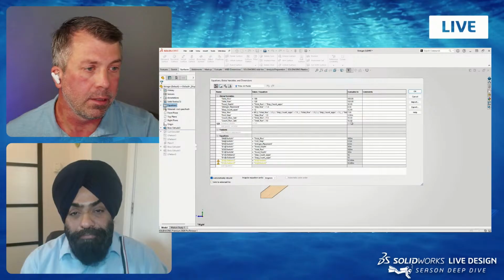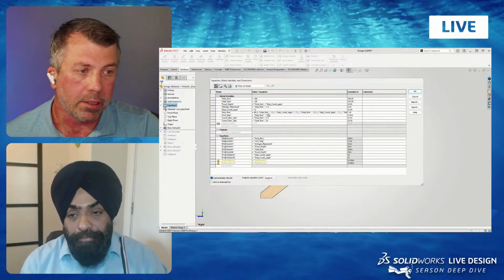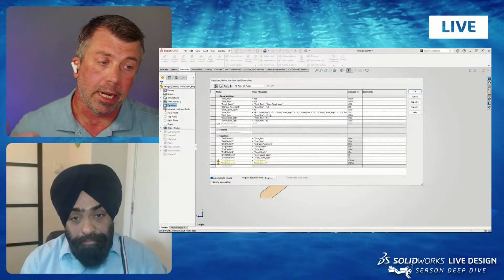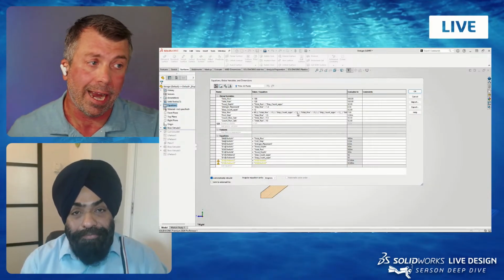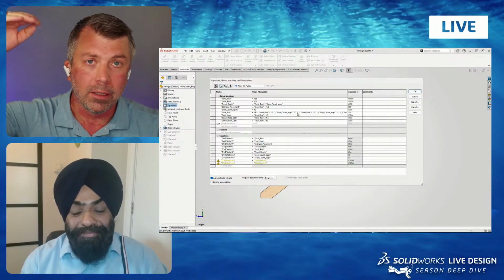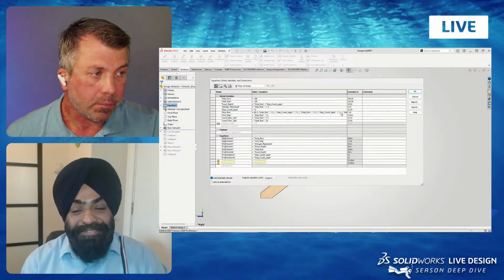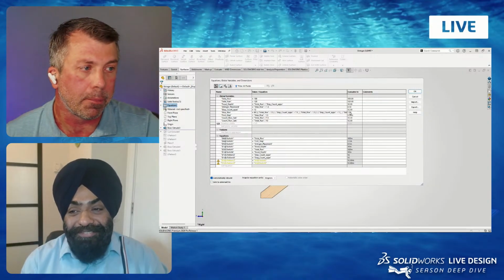Then I use step rise, and you can go a little beyond and use if-then functions, saying if it is greater than 7.5, that's too high, so let's add a stair, because then we need to drop that height. And this gives me my step rise.